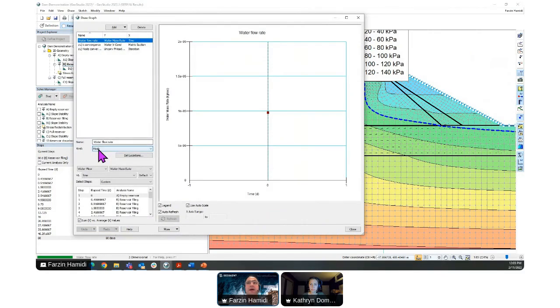So when you have a set location, you can check that under your mesh. You can select the water flow, whatever you were interested to see. I think you will definitely want to see the water rate. So you select that, and versus time you can draw that, and you will be able to select a time step.